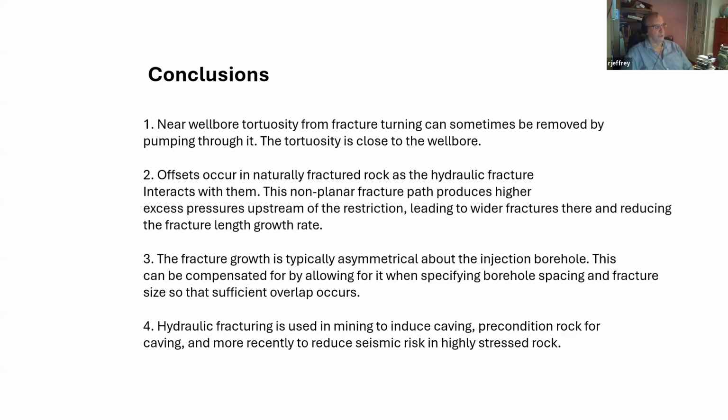We have done quite a lot of work, and when I was at CSIRO, we did a lot of laboratory work focused on that issue, propagating fractures through interfaces that were pre-constructed to have a certain frictional strength and orientation and placed ahead of the fracture path, and then carefully in our polyaxial frame, which takes blocks of about 350 to 380 millimeters on a side, we propagate the fractures through them and compare the results to Renshaw and Pollard, another criterion for crossing.